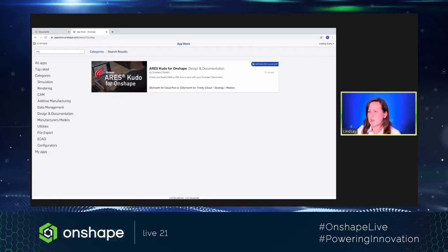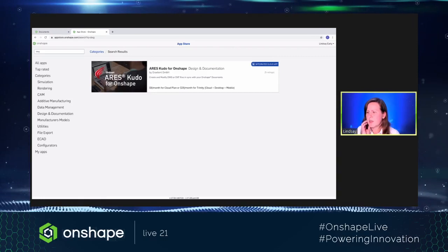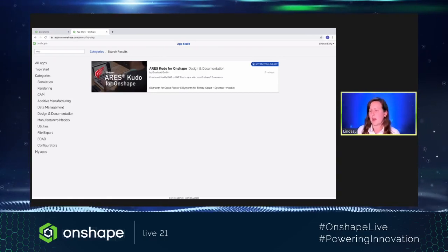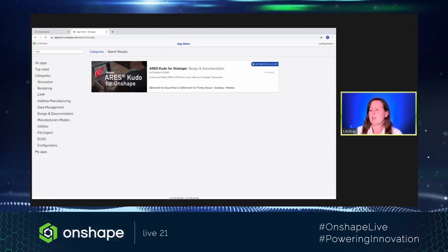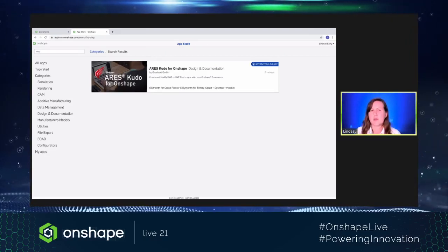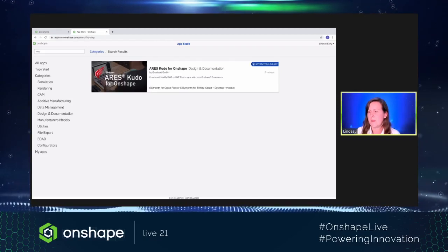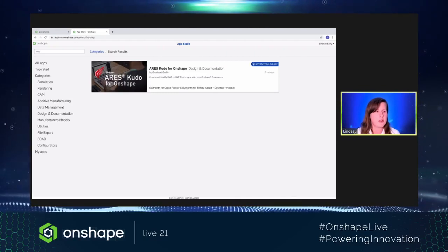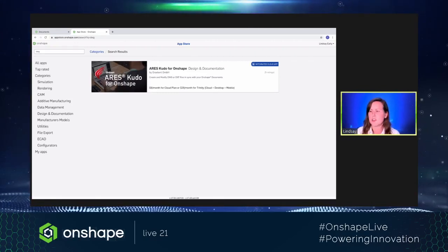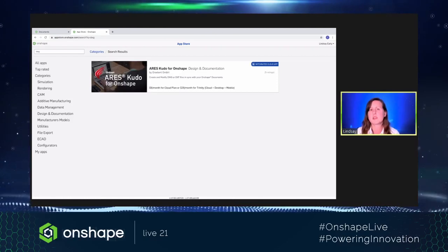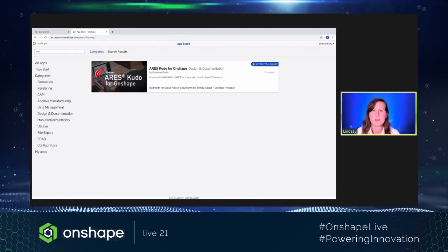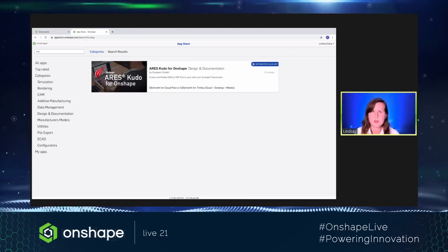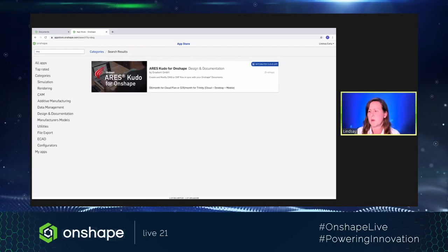So, purchased parts that we consistently integrate into our assemblies. Would we have to re-import all of these or do you have any digital part suppliers? So yeah, you'd have to import them. I don't know of anything in the App Store that would automatically import straight to Onshape, but you can just download a Parasolid. Parasolid is the best because that's the kernel that we're built on. So if you use a Parasolid, you should be able to bring it in. SolidWorks is also built on Parasolid, so SolidWorks files work great as well.